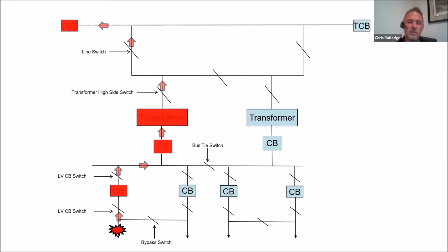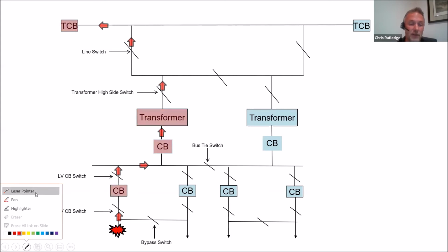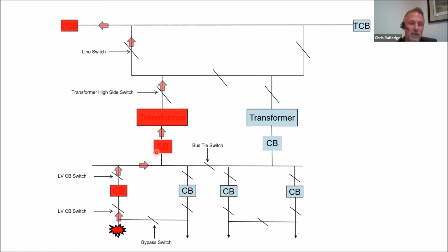There's always some type of delay that's going to be set between these breakers. You may have 15 cycles between your distribution breaker and your bank breaker. You may have another 15 cycles between your high side breaker and this bank breaker. So if this event occurs here and the breaker operates normally, we clear out in 3 cycles, we've cleared this fault. However, if this breaker were to be slow, this fault would have to sit on this breaker for 15 cycles before we would actually see operation of this bank breaker to clear this fault out.